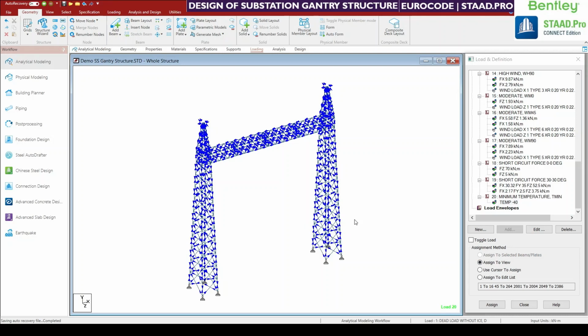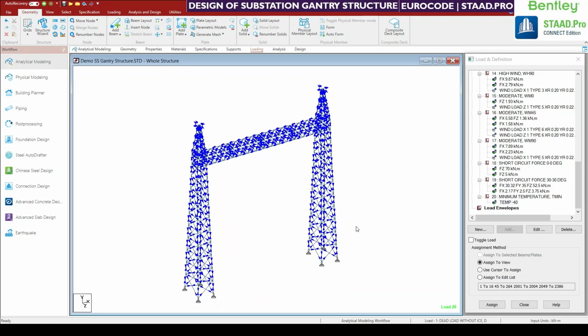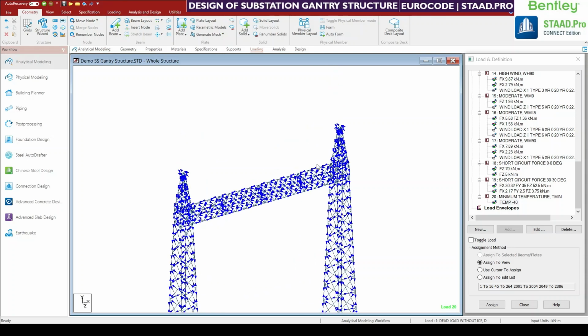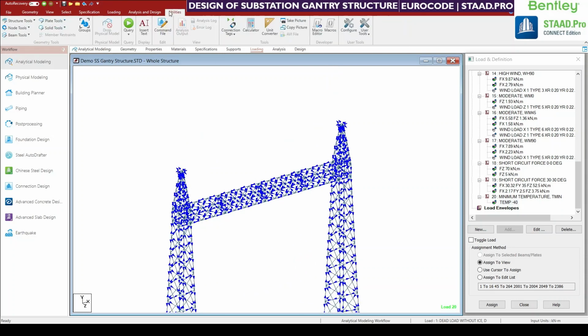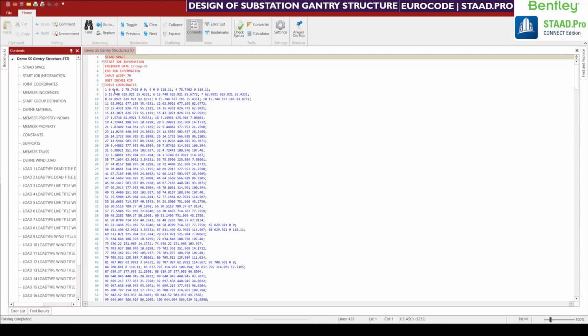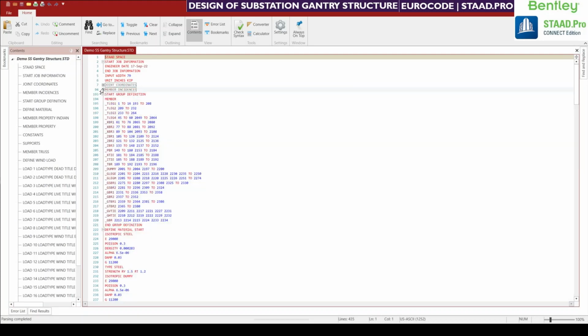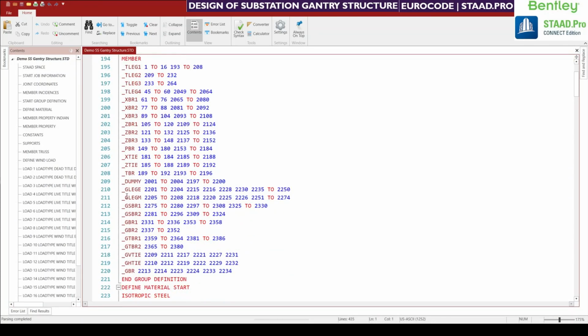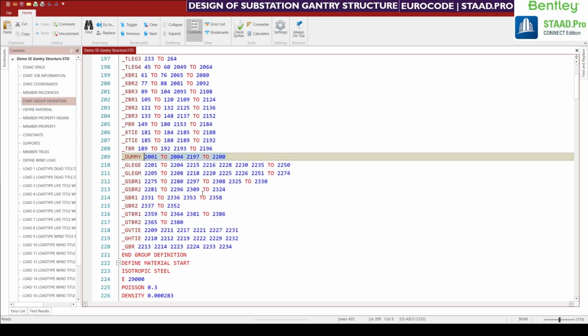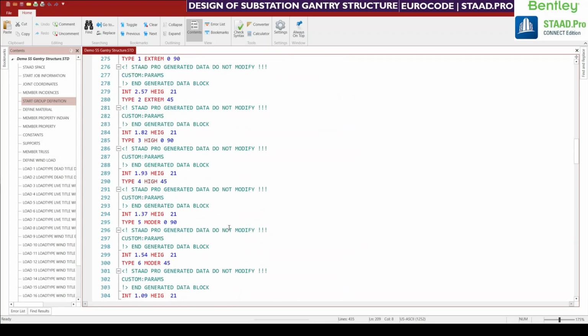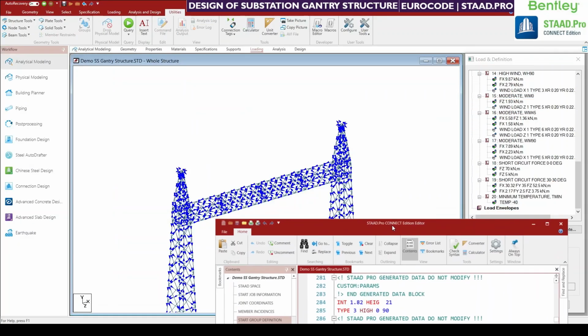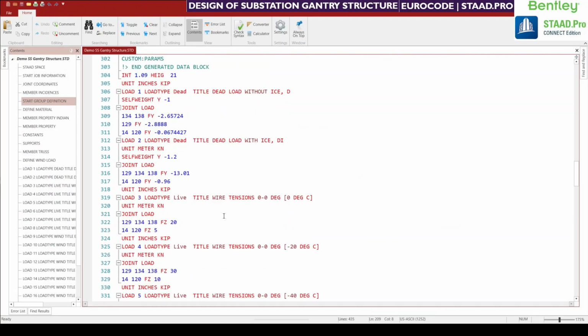So now the temperature load for structural members is added, but however we need to remove the temperature load applied on the dummy member. Click on utility, go to command. So we already defined the dummy member numbers which start from 2001. These are the members we need to remove now for the minimum temperature load case.